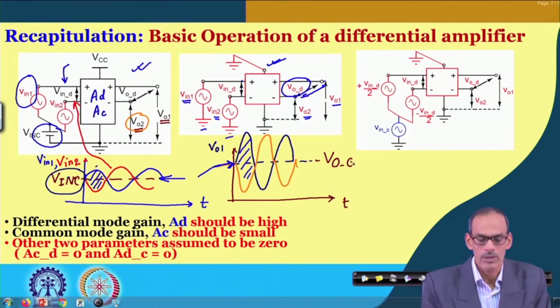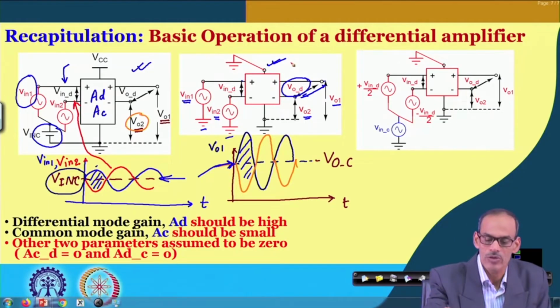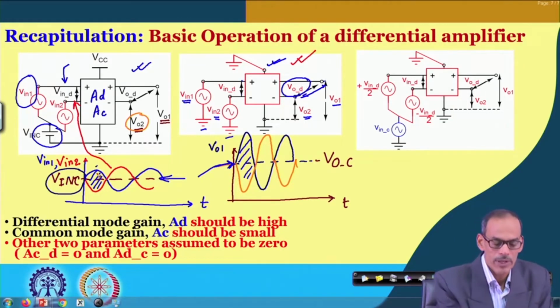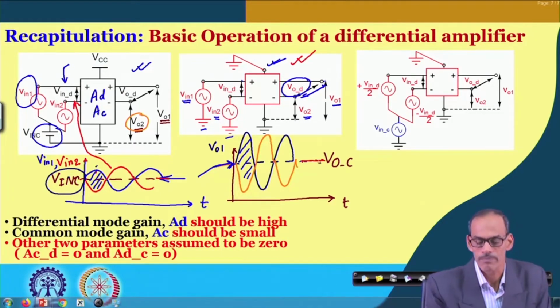And then, whenever we are at the small signal equivalent circuit, we are primarily focusing on the signal, and we need to adjust this DC level to ground level. Okay. So, same thing here also.